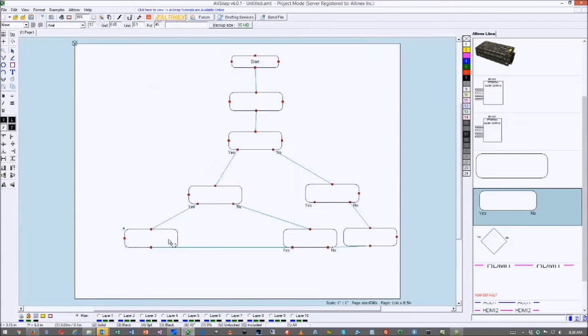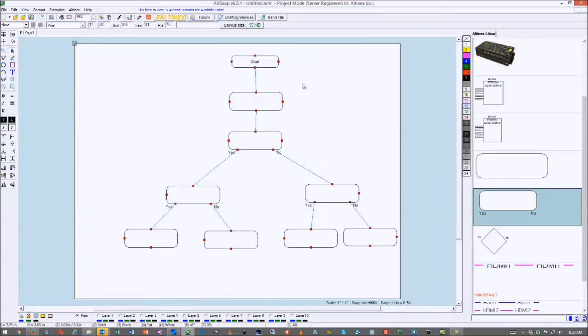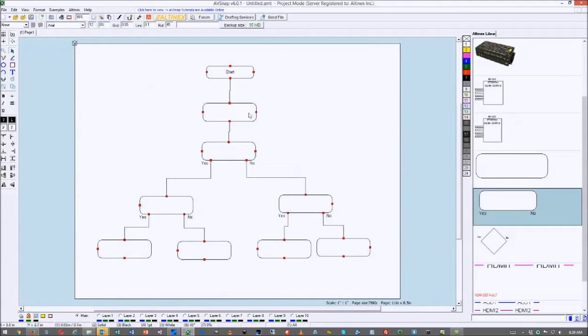Let's go ahead. We don't need decision blocks. We can just copy paste this, and no need for a decision block, copy paste this. Okay, and there we are. So you can see that automatically the flowchart was set up, and then right-click on the flowchart and auto route, and it will automatically route everything. So that's how quickly you can get from symbol design to flowchart to automatically routing it.